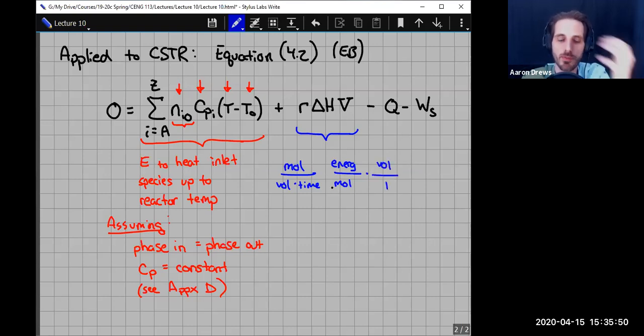If you lump all of those together, what you're saying is if I am producing things at a particular rate of moles per volume per time, and I use basically a unit conversion that says for every mole that I produce, I have a corresponding amount of energy, and that's our enthalpy of reaction, and I multiply that by how much stuff that I have, that's got to give me my energy production per unit time. And that's exactly what's being described here: if this reaction is occurring at a particular rate, and every time that reaction occurs, it gives a particular amount of energy, and I know I'm doing it in a particular volume, here's how much energy has to be coming out.